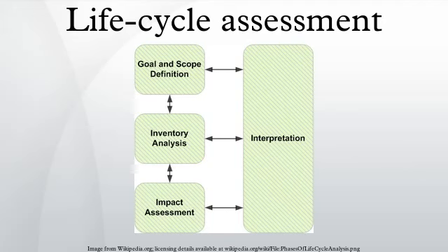Four main phases. According to the ISO 14040 and 14044 standards, a life cycle assessment is carried out in four distinct phases as illustrated in the figure shown to the right. The phases are often interdependent in that the results of one phase will inform how other phases are completed. Goal and scope. An LCA starts with an explicit statement of the goal and scope of the study, which sets out the context of the study and explains how and to whom the results are to be communicated.